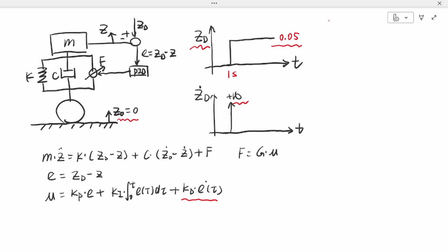So, how do we fix this? Since the reference value is arbitrarily changed by human command, it inherently lacks physical inertia. As I mentioned in the last episode, the physics of the derivative term is essentially acting as a damper. Instead of differentiating the unstable reference, why don't we apply the damping directly to the output result? The result here is our vehicle displacement Z. Because it represents a physical quantity with actual inertia, it can never experience an instantaneous jump.